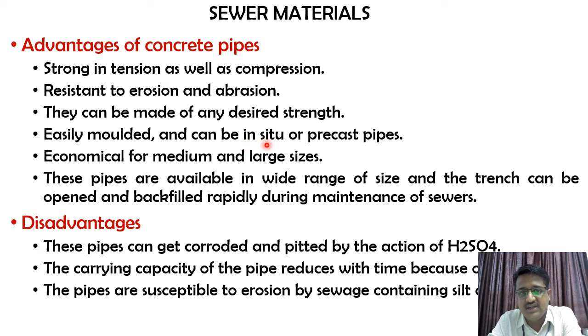In situ means, if the sections are quite large, at that point of time you can cast those pipelines at the site itself. Or precast pipes, where the same diameter is maintained for a long length, at that point you can have precast pipes. Economical for medium to large sizes.